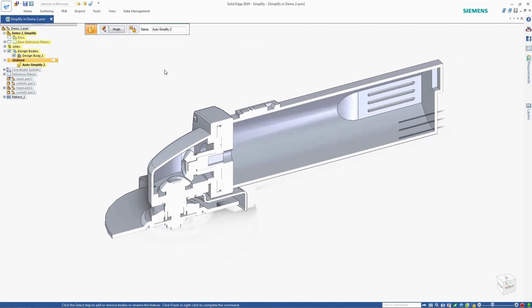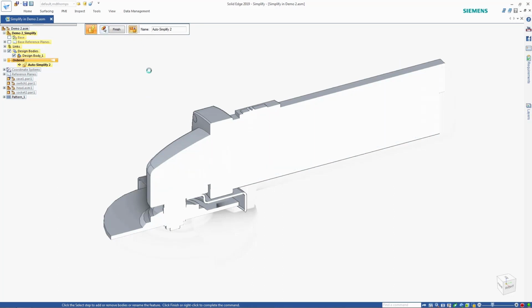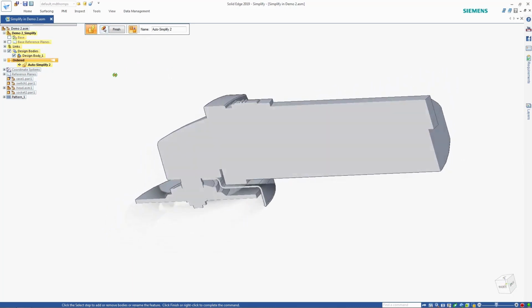Part files have been booleaned together to create a continuous connected part file. Internal voids on each part have also been filled in. Now, if we want to remove all voids and completely fill in the entire assembly, we can toggle an option on the command bar to do just that.